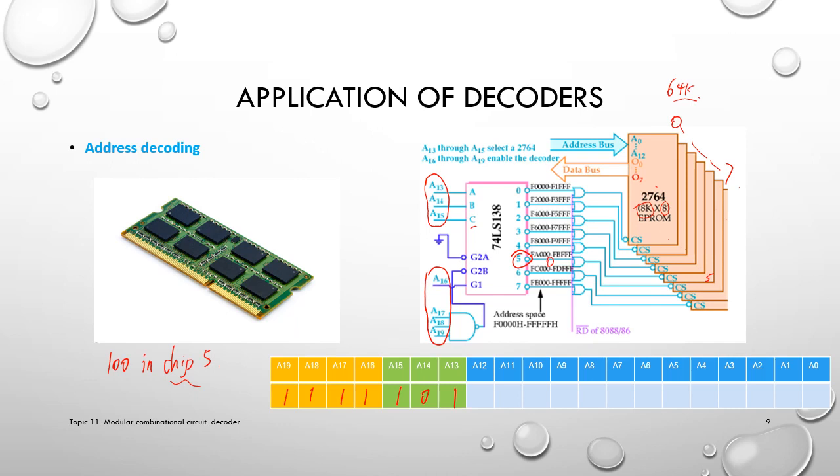By the way, before we do the read operation, we need to set this read enable to 0. You see it has a bar there, which means active low. We activate the read operation. This read line is connected to the other input of the OR gate. So we have 0 and 0, and we will get a 0 here. This 0 can activate this memory chip, because this CS is the enable input for this chip, and it's active now. So 0 will enable this. Sorry, that's the wrong chip, right?